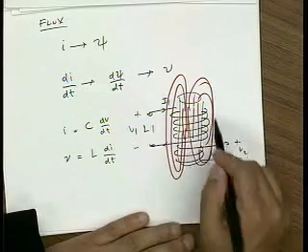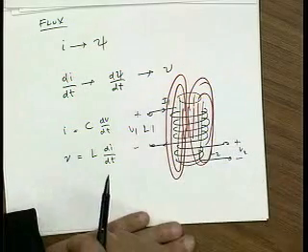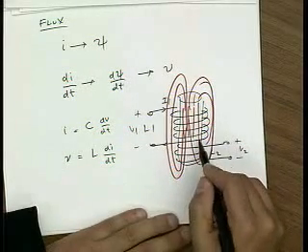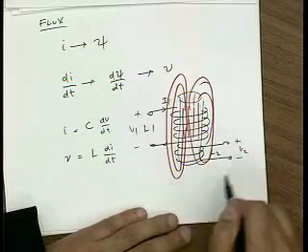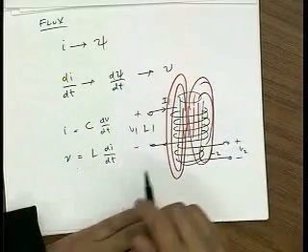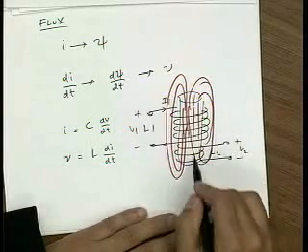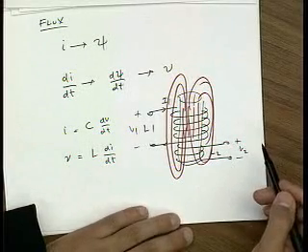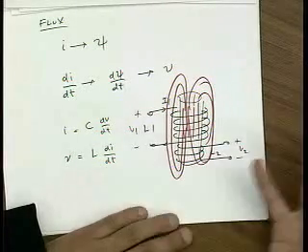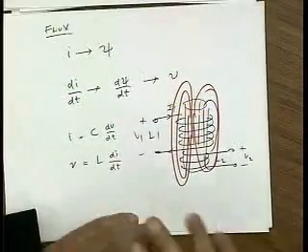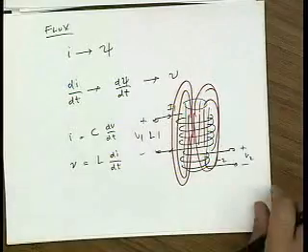If all the flux from one circuit enters the other circuit, then the K factor approaches 1. If the flux intersects another circuit with the opposite orientation, as I've shown here, this circuit is wound in one direction, this one is wound in the other direction, then a positive flux here corresponds to a negative flux in this circuit. And that could make my mutual inductance negative. Or if you like, you can make K negative. You can either absorb that into K or into M. So I can also induce negative voltages. So I can easily flip voltages around using transformers, using coupled inductors. Okay. Questions?